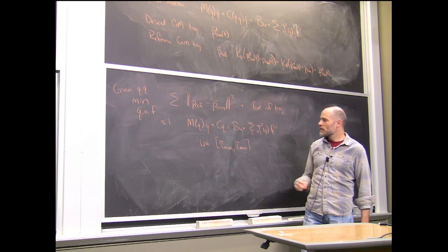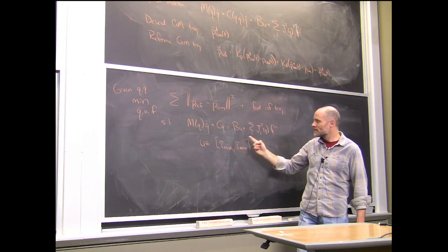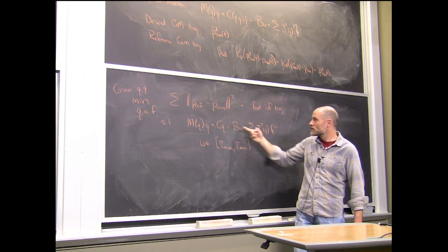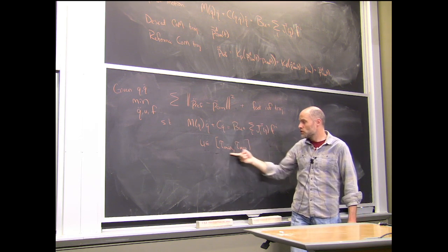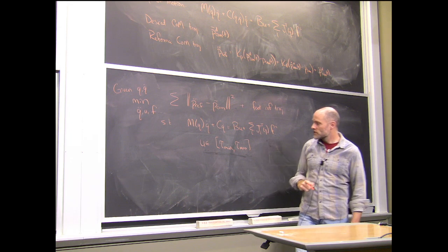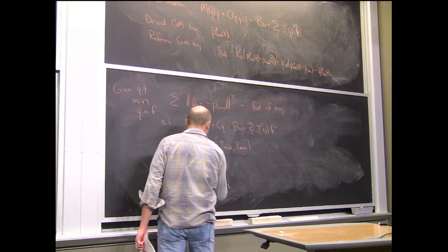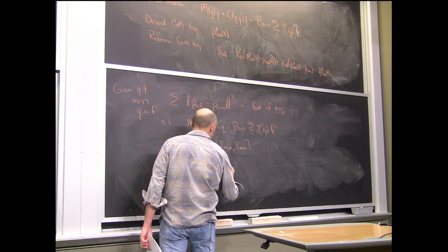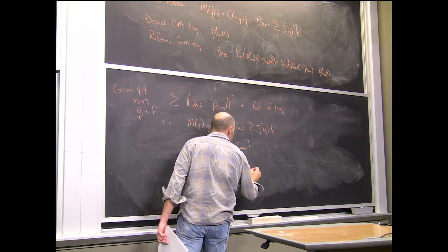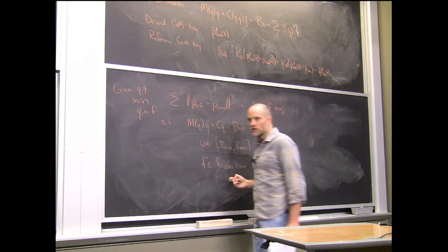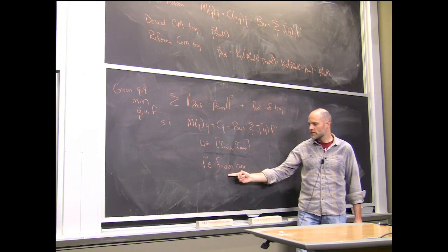Actually, if it was only these equality constraints, I could potentially just solve it in closed form. But U is an inequality constraint, and the other one we add is that the force has to be inside the friction cone. That's the biggest reason why we end up with a quadratic program instead of an unconstrained least squares.